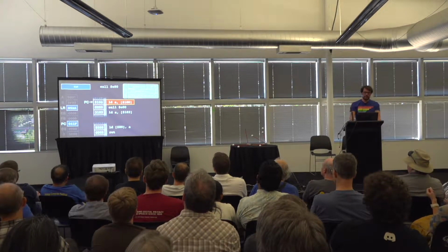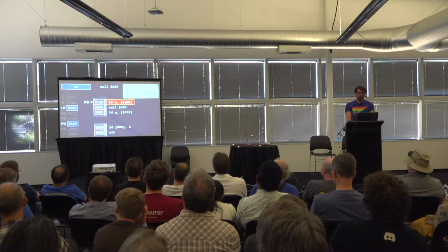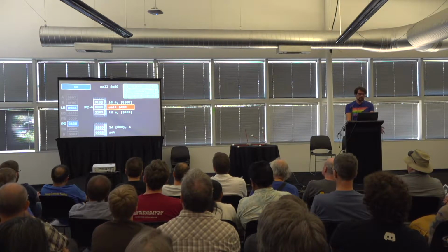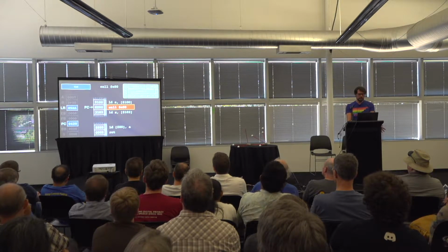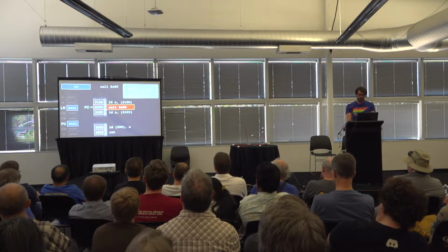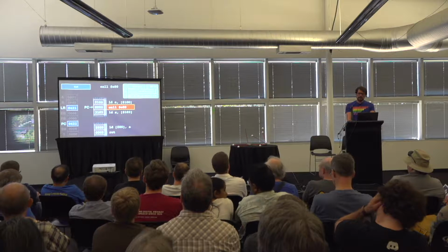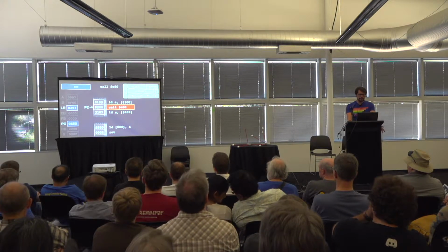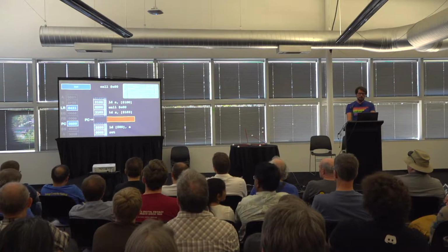The call instruction is meant for calling subroutines, aka functions. It is like a jump instruction, but it saves its origin, so the callee can return to it later. For the call instruction, the program counter is incremented first and then copied into the link register, LR. Finally, the argument of the call instruction is copied into the program counter so that execution continues there. The link register now contains the return address.